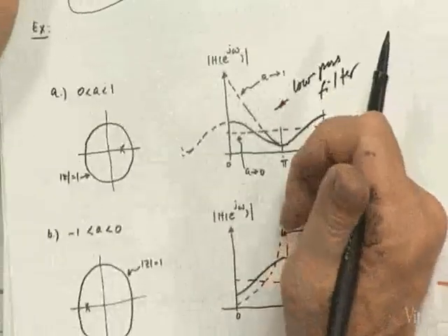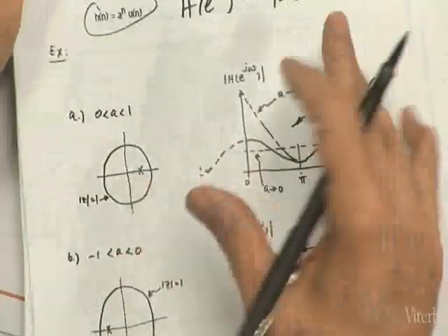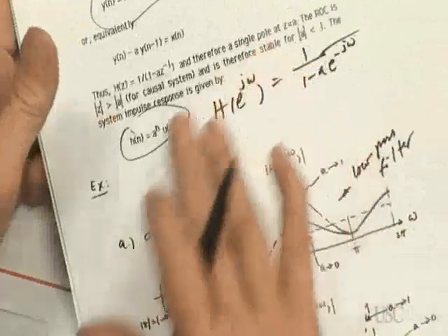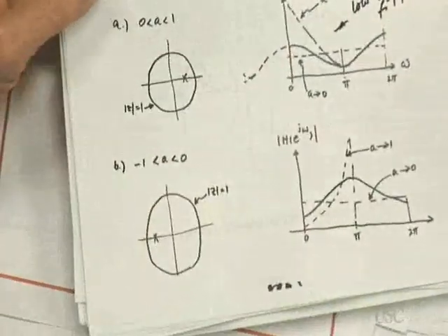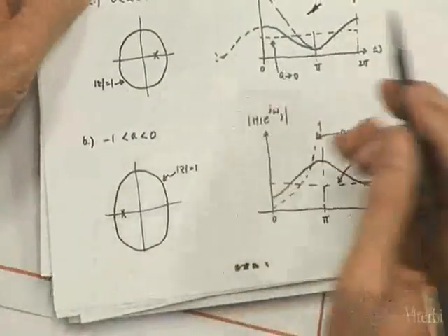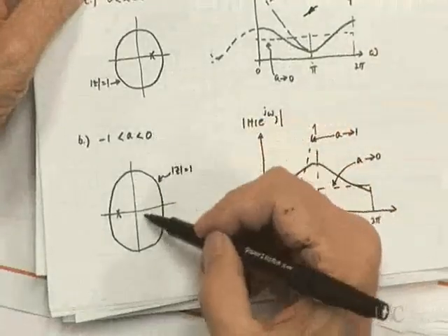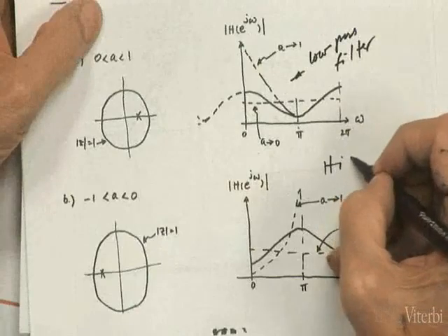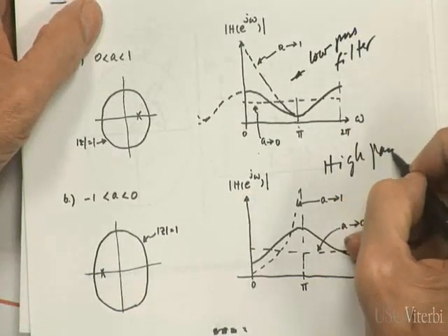It's just with a different parameter. That's why people like these simple recursive filters. I use these low-pass filters all the time if I want to do some simple smoothing. And if you may recall, if a is negative, then you get something that we called a high-pass filter.